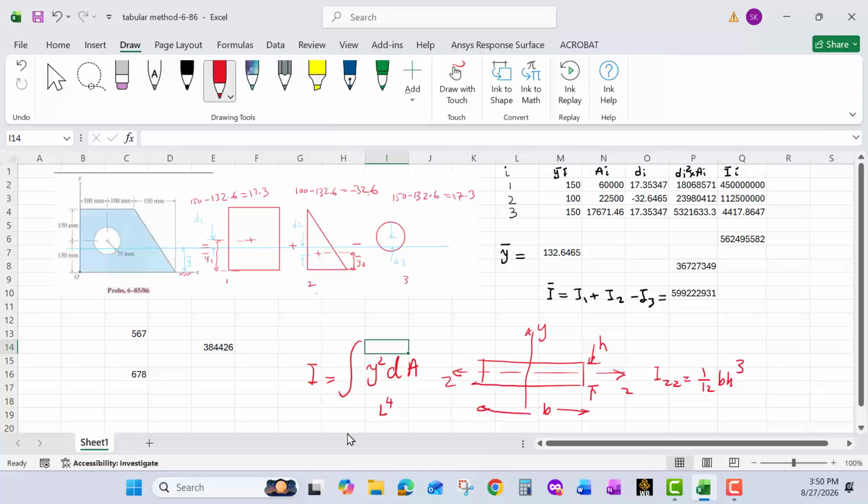The neutral plane generally coming from the table is located at the centroid of the decomposed shape, for example here. And that decomposition has an offset with the centroid of the composite shape. For each shape, you have to find that offset and use it for calculating the penalty or error to be added to the standard moment of area before you combine them together.